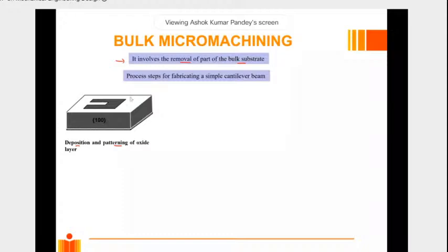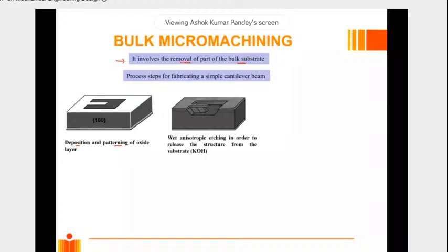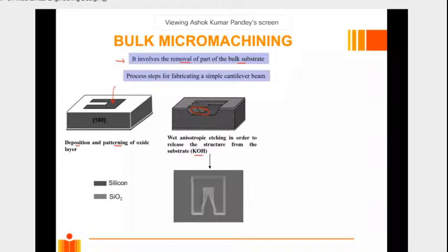After going through this process, what you get is, let us say, the material which is not exposed will start etching away, right? When it etches, you see that sometimes it doesn't etch completely. Some of the material underneath will remain there, right? So that is a problem. It means that if I try to etch this with KOH as your etchant, you will get this problem, right? And if you see it from the top, you see how this material remains over here, right?